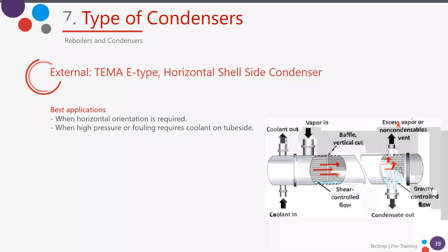So it is always necessary to take out all the non-condensable vapors from the shell and tube condensers. And also here at the inlet, an impingement protection, as we saw in the first session on shell and tube, is required as vapor enters the shell side.